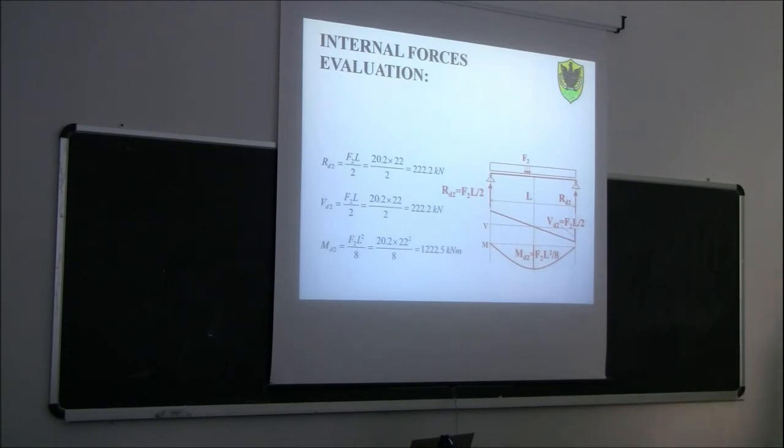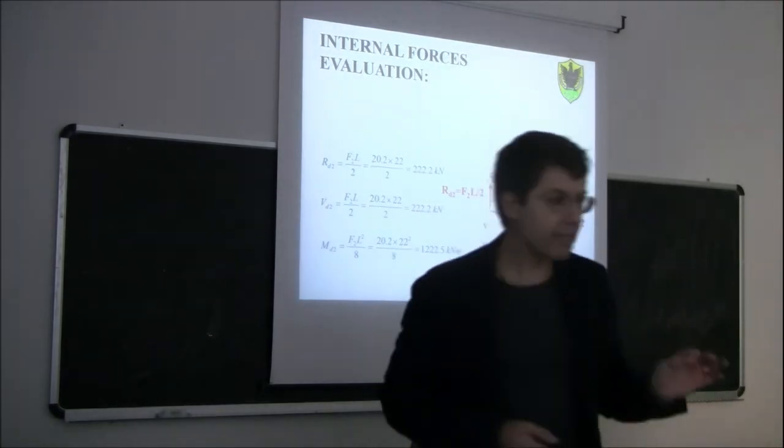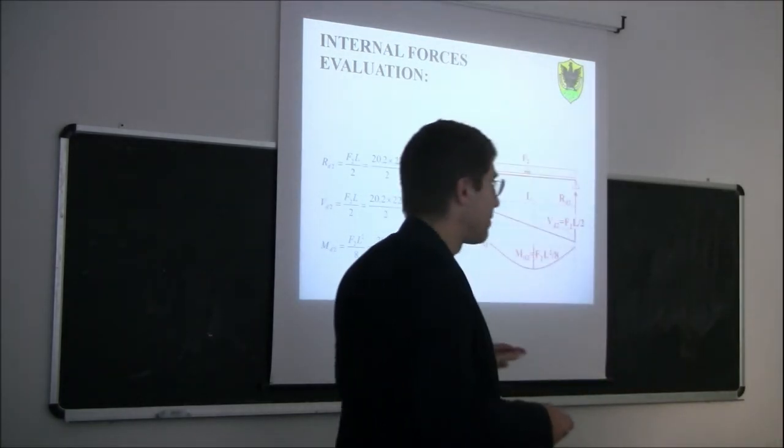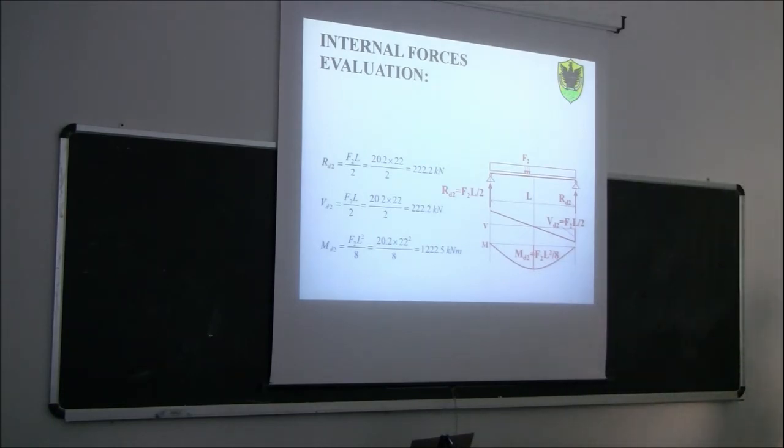So we don't consider the bending moment demand and compare it with the bending moment capacity, but we go back to what we used to do with the permissible stress method. So we compare the maximum stress in the most stressed point of your volume. We compare this with the design strength of the timber at the local level. Okay?